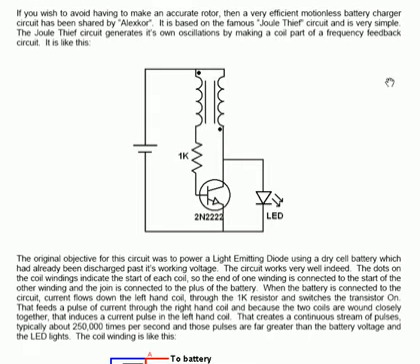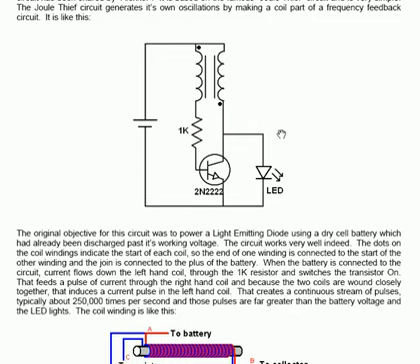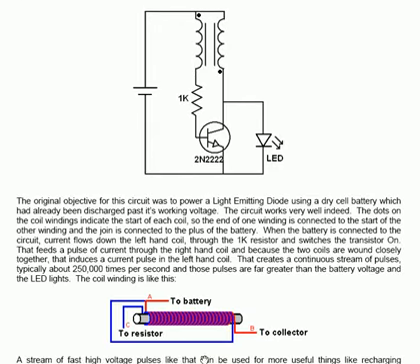There are two windings which are positioned together. In fact, the two windings are shown here in this diagram, one in red and one in blue. The two windings are connected together, but notice the dots. These dots indicate the start of the particular winding. So the red wire is wound side by side with the blue wire down the length of a tube or former. At the end of this, the end of the blue wire is connected back to the start of the red wire. Those two wires joined together are then connected to the plus of the battery.